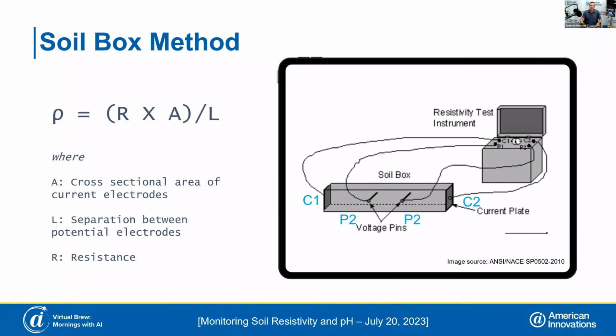From my experience, it's really kind of a negligible thing, because with the pin lengths and their depths, you really want to just get it deep enough that it's going to stay in place. But the depth that you're generally trying to get a sense of the average soil resistivity is much larger than the depth that the pin is going into the ground.